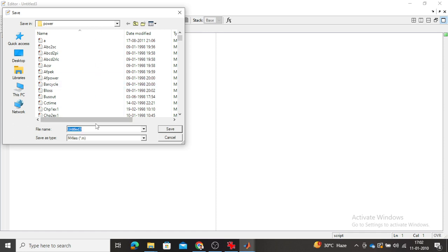So there, instead of untitled 3 or untitled 1, you can rename it, but do remember MATLAB is case sensitive, and the starting name of the file must be an alphabet. It should not be a numeric. If it is a numeric, it will be treated as a calling function and the output will not be shown. Okay, the program will not be executed. So the starting letter must be an alphabet. However, the second, third and the rest, you can keep either numeric or anything, but the first one must be an alphabet. So experiment, exp1, like that.